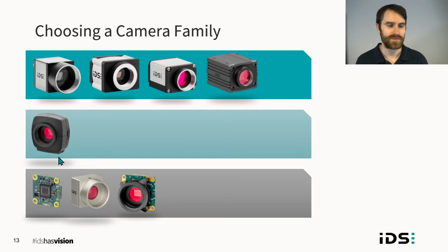They have image memory on board, so they have enough to store some images in case there's a collision on the bus. And they are also FPGA-based cameras. So that means they have that precision needed for synchronizing multiple cameras together.